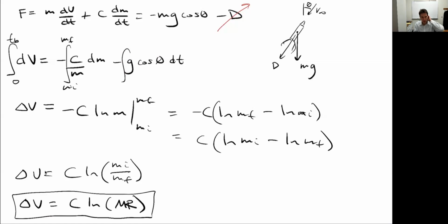And they can also give us an idea about the magnitudes. So for example, to get into low Earth orbit, it takes a delta V of about 9 kilometers per second. That's what I need to achieve here if I want to get to low Earth orbit. That's actually quite a bit. So getting away from Earth takes a ton of energy. By contrast, to get to Mars is actually not that much more delta V. It's like 10.4 or something like that, right? Whereas it takes 9 kilometers per second just to get to low Earth orbit.